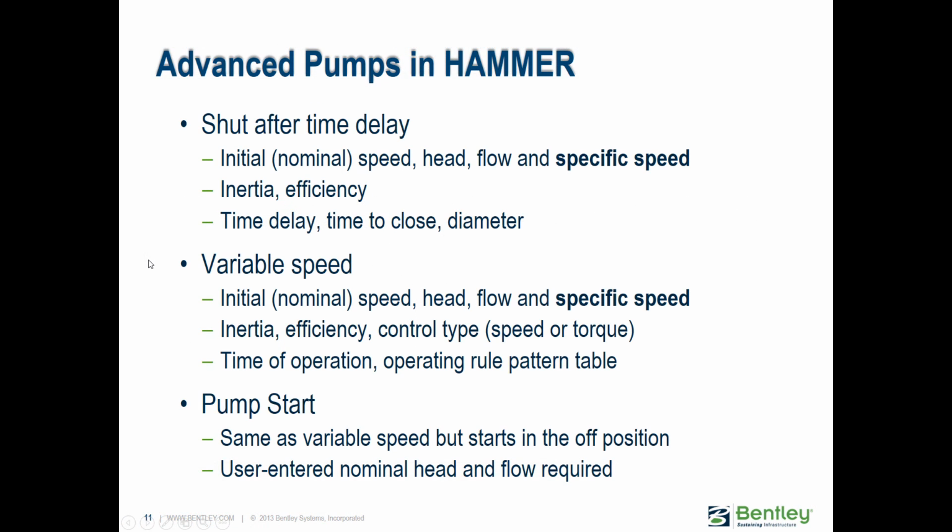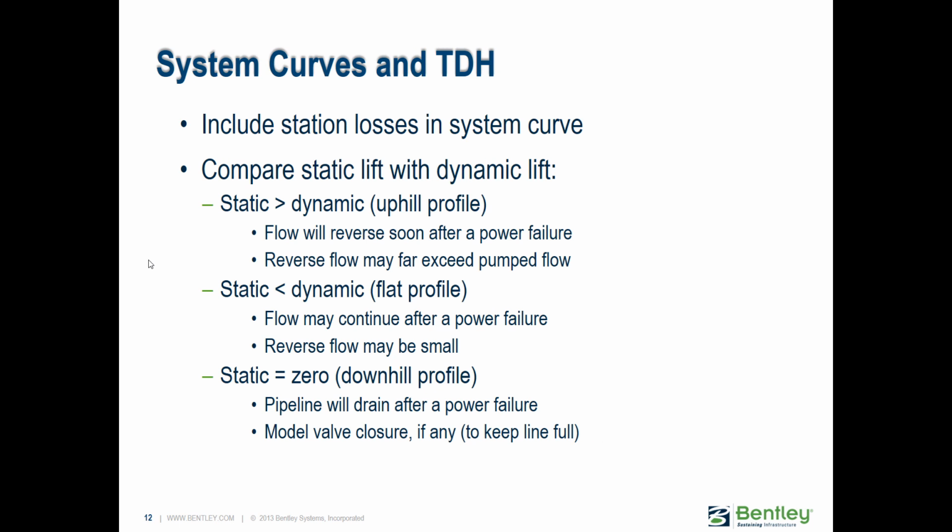So variable speed and pump start are pretty much the same. In both cases, you're specifying a pattern of how that pump changes over time, as I was saying. And there are some articles, again, in that additional resources module on the right side that go into a little bit more detail of the different types of pump events.